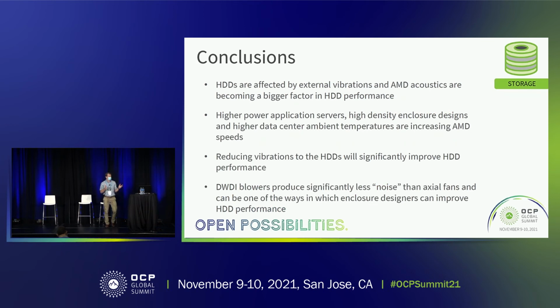So in conclusion, I think all of us, or most of us, know the HDDs can be affected by these vibrations. They're sensitive to it, and it's becoming more of a problem with the axial fans coming at higher fan speeds. Higher power applications, servers, more density, and higher ambient temperatures are causing these fan speeds to increase.